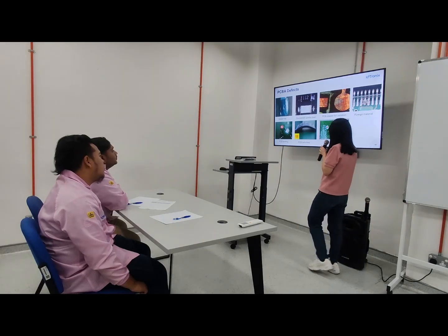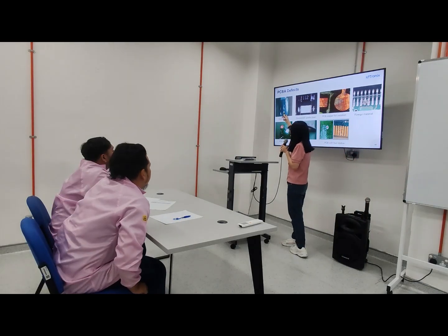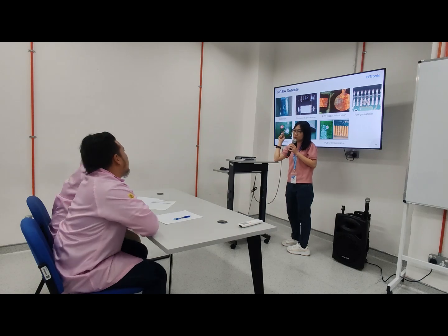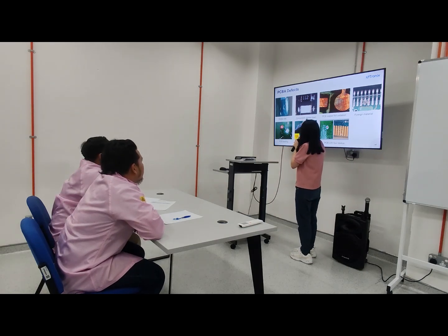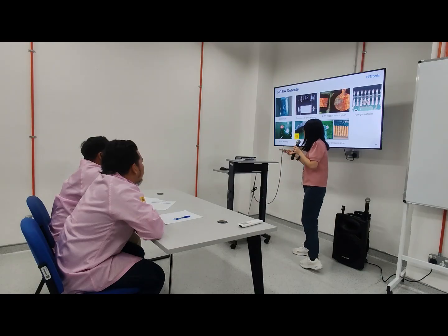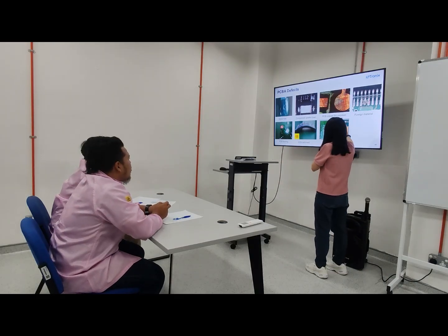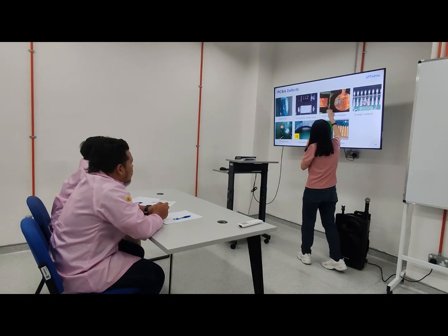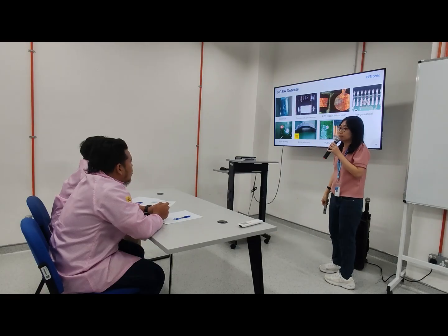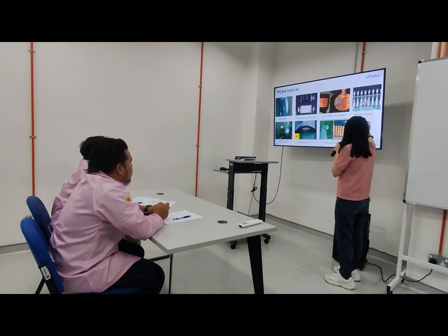Okay. This one, PCB solder hole. There is a hole with solder. This one is also double accept. Next, component upside down. Reversed is supposed to be like this, but here it's already reversed. It's the PCB copper foil oxidation. You know, this area, the copper is now oxidized. Next, the foreign material. Foreign material here.